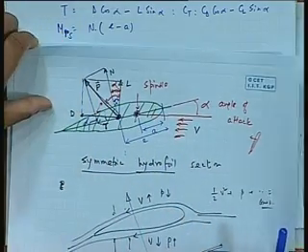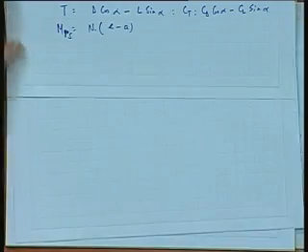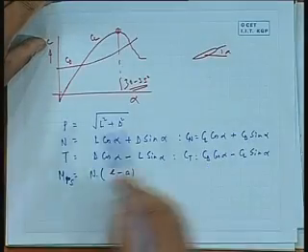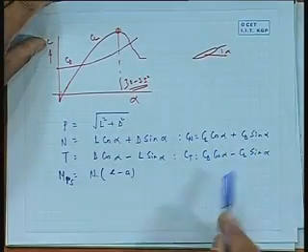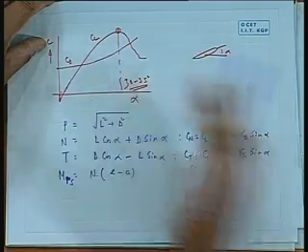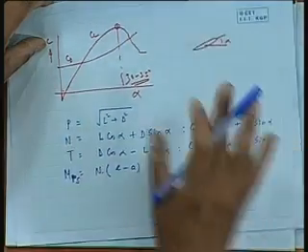Why I am saying that is because in the rudder design we will find out that essentially if you can estimate this L etc. from every section, you can integrate and you can get the entire rudder's performance. The hydrodynamic performance of the rudder can be obtained by actually taking section by section the CL, CD values, and then of course adding up all.